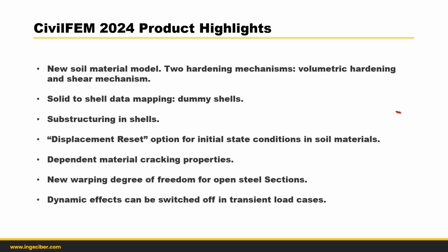New CivilFEM Soil Material. This material model incorporates two hardening mechanisms: volumetric hardening, which is governed by compressing state, and the shear mechanism that produces soil stiffness reduction, plastic strain, and dilatancy.